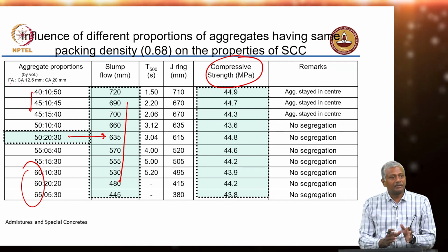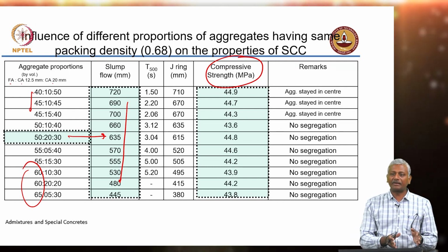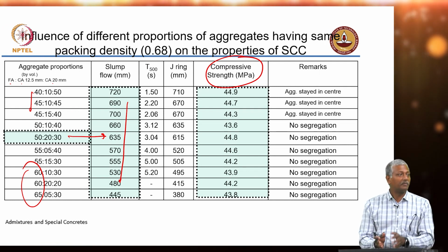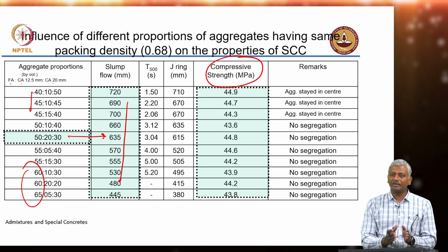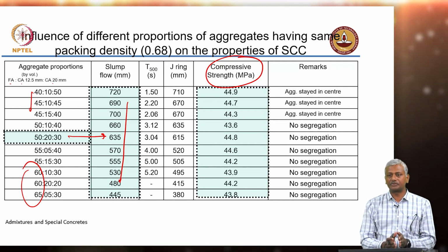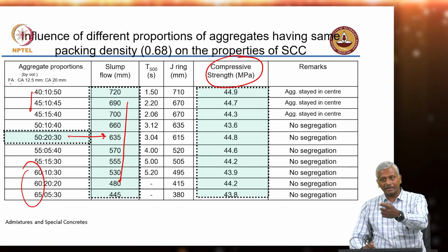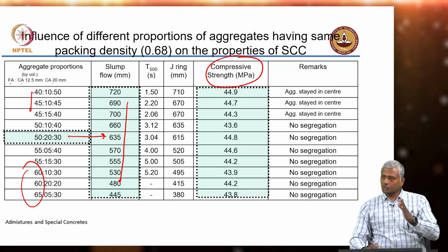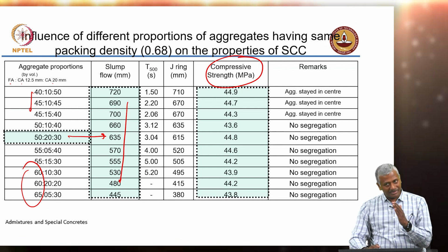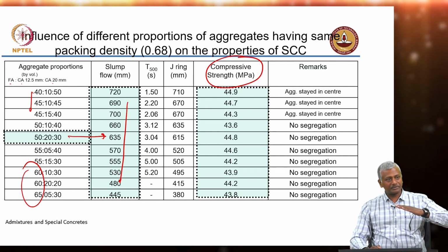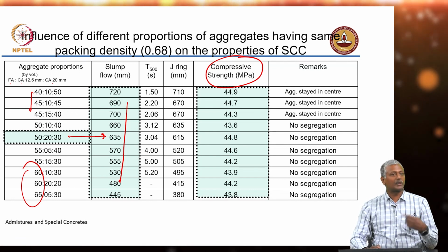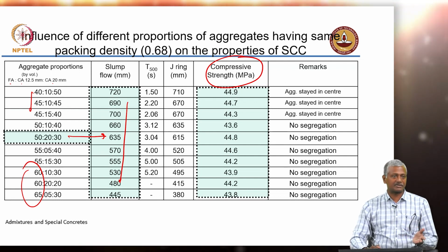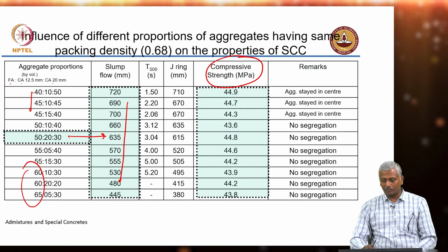Okay. So, again upshot is at the same packing density irrespective of aggregate combination, you will get similar strength, but your workability will depend on the combination. So, you have to be careful. So, again if you remember, I talked about the same thing when we discussed particle packing also. By choosing different Q values, you are increasing packing density, but you still have to look at how to provide the workability, and that is where your choice of super plasticizer, rheology of the concrete become very important.